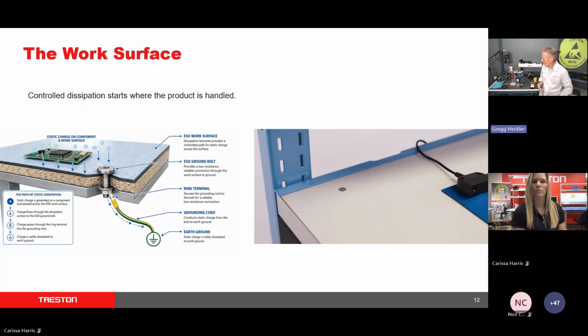It's the same thing with a soft mat, for example. I got this one connected to a continuous monitor, but we use snaps and ground cords, for instance, on a soft mat material. And if you have a 3-layer vinyl material, you can barely see it, but underneath the surface, there's that dark gray line. That's the buried conductor in the 3-layer material. And we need to make contact with that. The way we do that is with these snaps that have what we call push and clench snap teeth. So they bite through and make contact with that surface that's necessary.